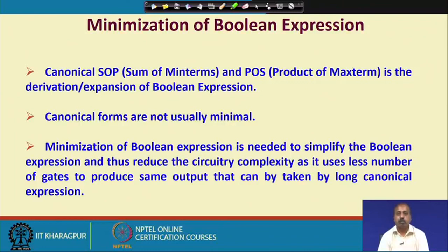In our course, we will be considering Boolean expressions with fewer variables, only 4 variables, 5 variables, at most 6 variables, and we will see that there exist exact methods for getting the exact minimum form corresponding to those functions. However, those methods are not applicable for more than 6 variables. If you are looking for a larger number of variables, then exact methods do exist, but the problem is that they take an enormous amount of time, even if you write a computer program for the minimization process.